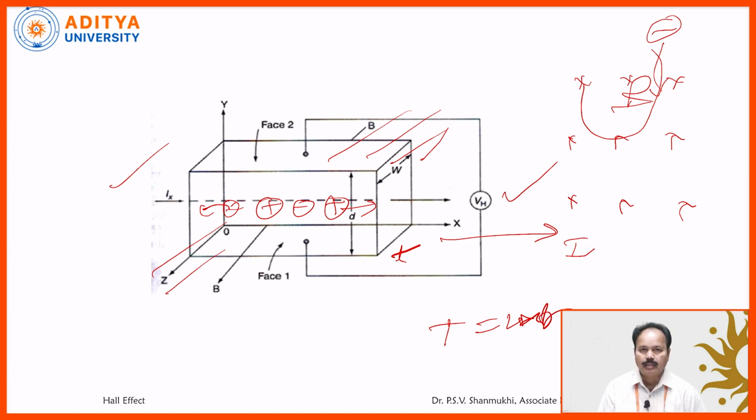In the transverse magnetic field, the charged particles will describe a circular path, which means they will be continuously deviated. Suppose the holes are deviated in the upward direction and electrons are deviated in the downward direction. After some time, holes are accumulated on the upper surface and electrons are accumulated on the lower surface.